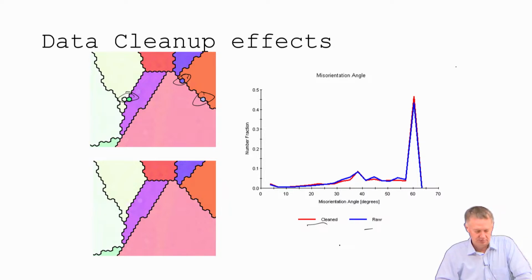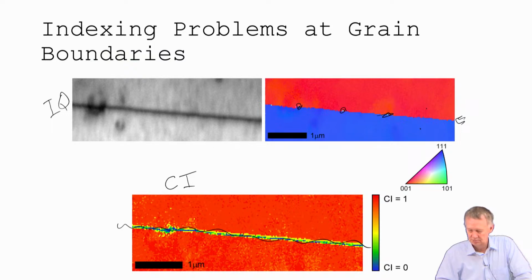Those points in the boundary on the previous slide, they look almost periodic. Yeah. Could those be grain boundary dislocations? I mean, grain boundary dislocations you won't see in EBSD, but if you have dislocations that accommodate the misfit, it could further interrupt the diffraction that's there, and so you might have lower quality diffraction at specific points, and they turn out to give you a specific value.